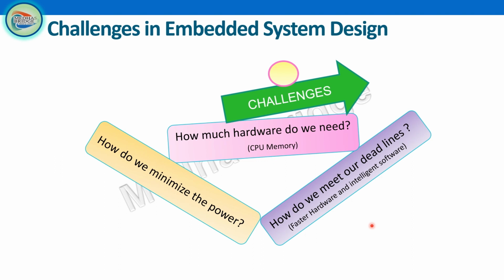You need to understand how much hardware is required: how much CPU, how much memory, what interfaces are needed, things like that. Also, an embedded system should run a long time, isn't it right? Power consumption is a concern because some embedded systems operate with solar systems, some operate with a battery.